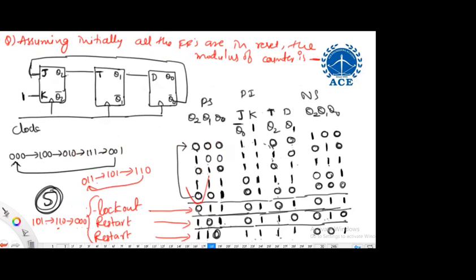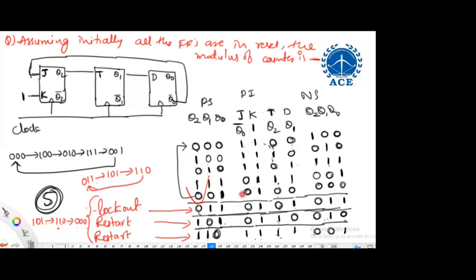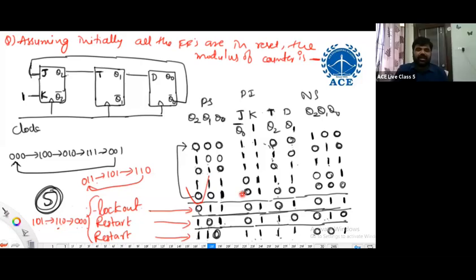Sir, then we won't say irregular order, right? A modulus counter will not be in an order, sir, like bits. Actually, what you think about modulus, the mathematical modulus, is wrong. With respect to a counter, what I discussed is the number of distinct states the counter is going through. Did I say that it is a mathematical modulus?